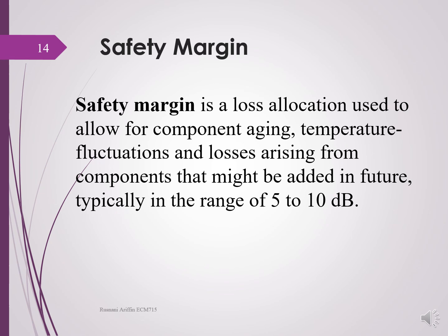Now let us look at safety margin. Safety margin is a loss allocation used to allow for component aging, temperature fluctuation, and losses arising from components that might be added in the future. The typical value is between 5 to 10 dB.